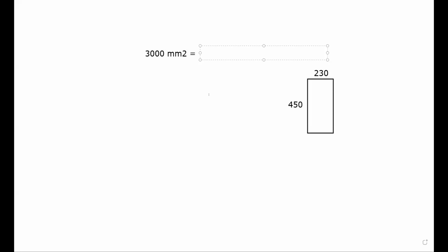First of all, minimum steel is a condition where, if the loads are lesser and steel is not required, since you do not have that much load, the minimum steel governs. So the software will automatically take it into consideration. The minimum steel is the condition which automatically by default applies: if the load is only 10 kilonewton on the column and your column is such a big column, then no need of steel, right? But as per the code, the software will calculate. It will assume 0.8% and then automatically for that 0.8%, it will calculate the area of steel.